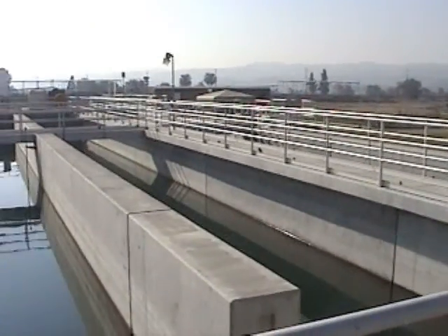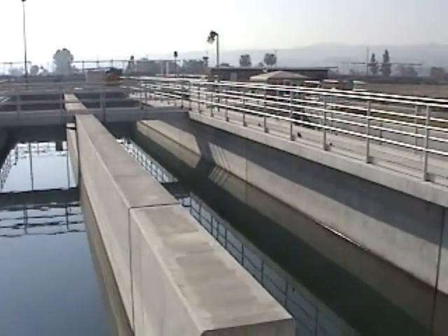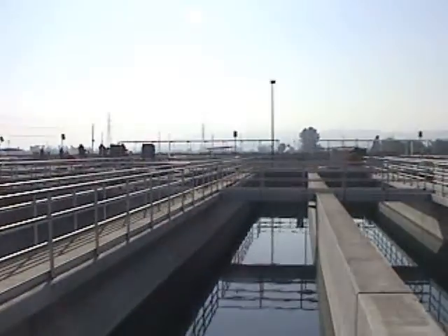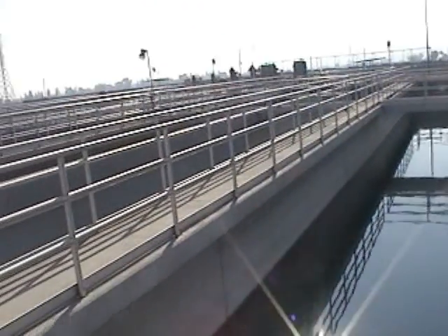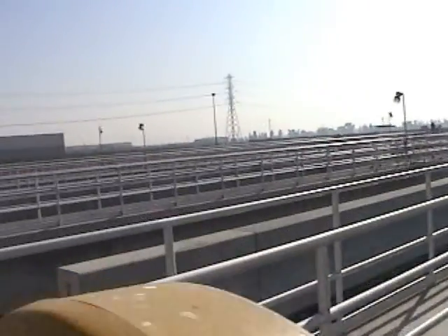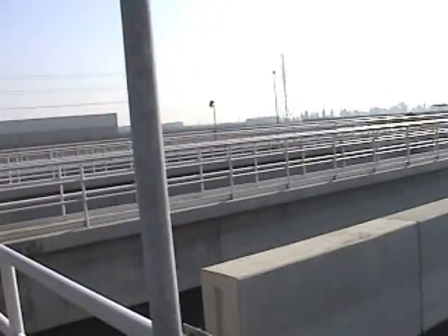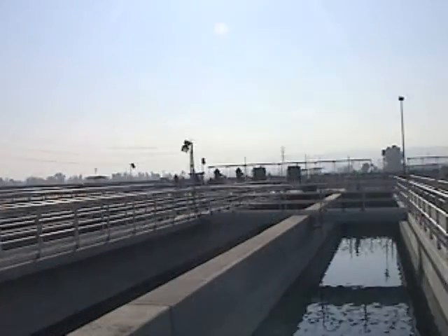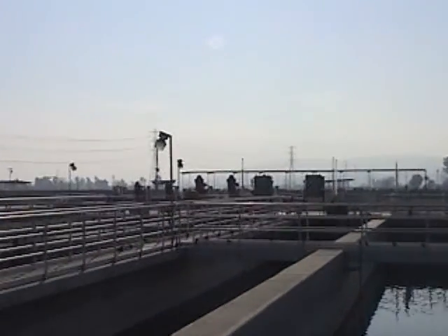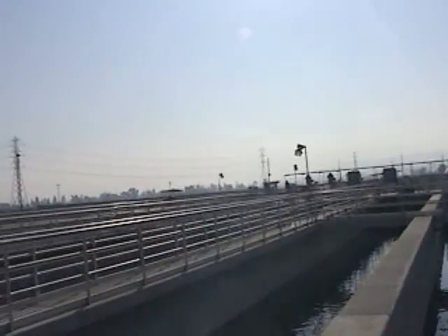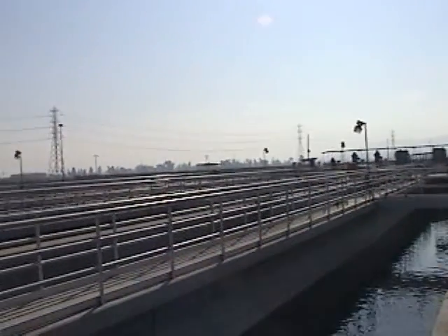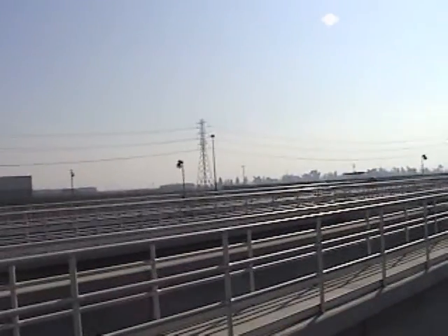And we figure the detention time on here at our current flows is about 4 hours. So it's going to serpentine through this tank, and then it's going to exit the chamber out on the south end down there, where we measure it for chlorine residual again. They have effluent analyzers, an east and west effluent analyzer.